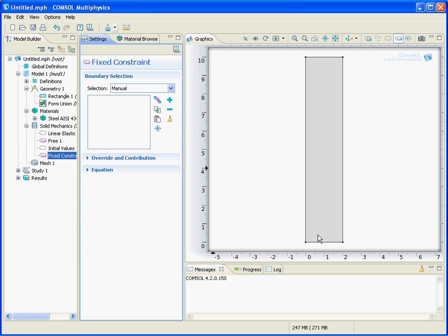So what this does, I'm going to click this boundary and add it, and it gives it this fixed position. If you wanted to add a force going up and a force going down, it doesn't have any reference to judge where you're pulling it. The whole piece is just going to move. So let's say in reality this beam is feeling force down in the Y and up in the Y at this boundary. You would have to fix it somewhere and then give it twice the force here, or however you want to do it. But you have to fix something; that needs to be the first constraint you add to it.